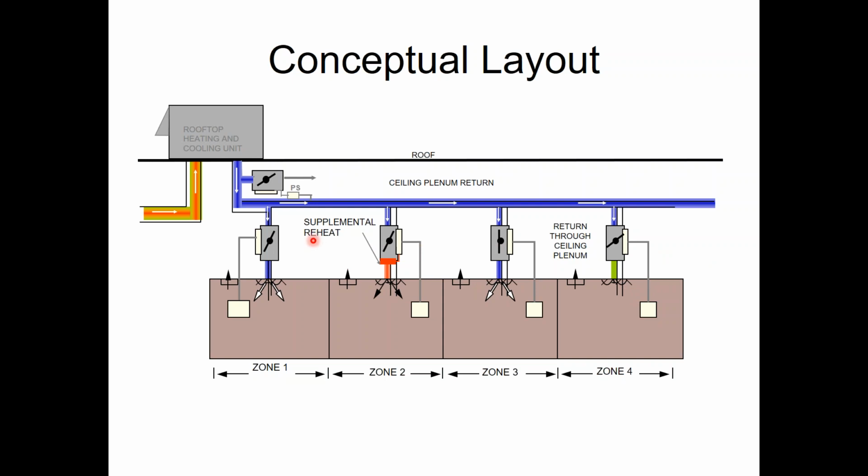Very similar to what we do on a VAV system, at least traditionally on a VAV system. Now, for you guys that joined me last week, know that the code requires a specific set point of 1.2 inches on all VAV systems. But prior to that, we would set the static pressure set point on the VFD of a VAV with the air balancer's help. And we're going to do the same thing now on the VVT system. We're going to make sure we can get the air volume that we need to all of the zones and no more than that. There's no reason for me to do more than that.